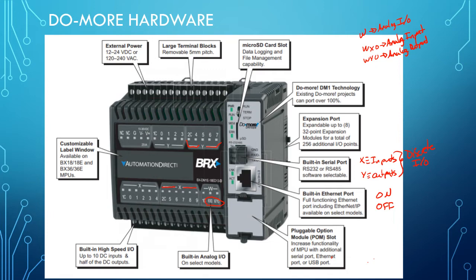So analog values are values that are numerical. It's not just an on, off, 1 or 0, which might be represented like this. Also, when you have 24 volts DC, that might also be represented that way. So on the analog, you might have a value, let's say you might have pressure values that range from 0 to 2000 psi.